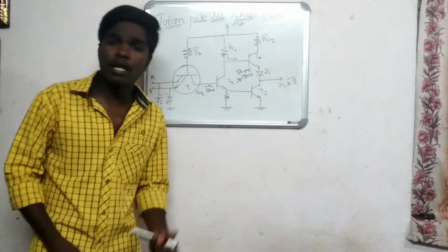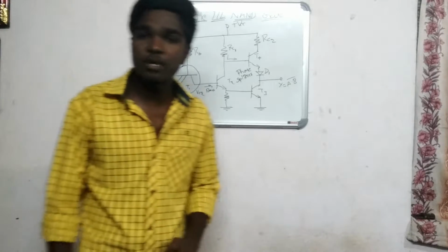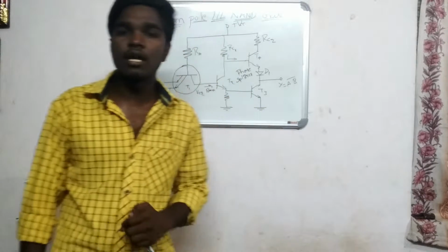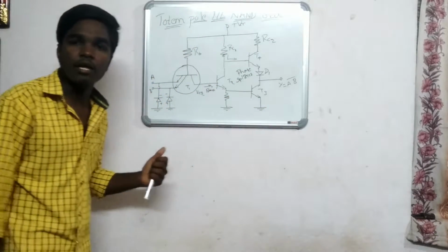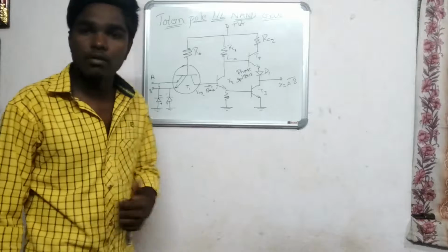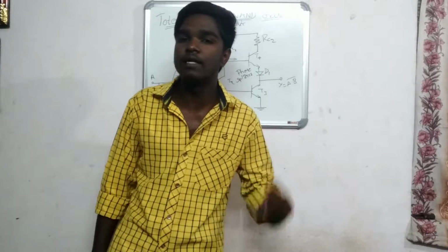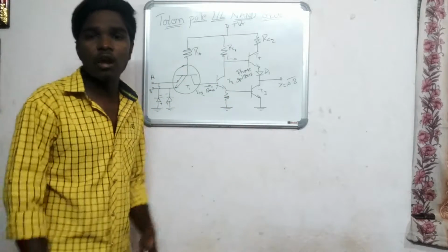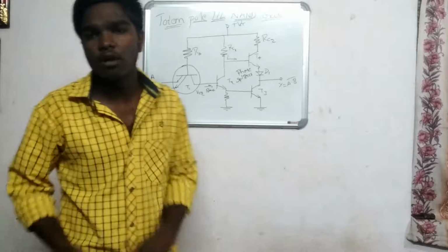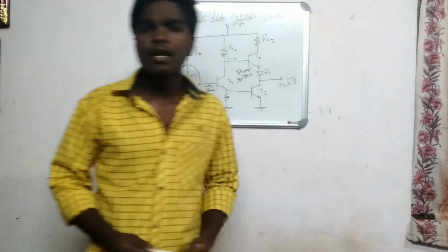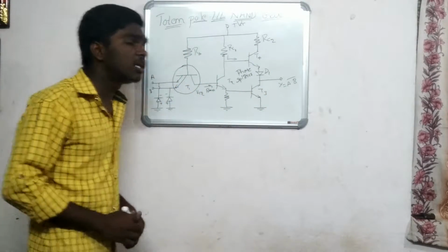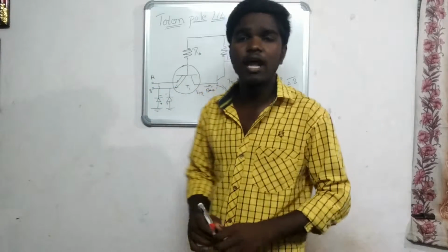We already discussed that the specially designed double emitter transistor T1 is arranged at the input side, and in this type of TTL NAND gate we are using three transistors T1, T2 and T3. When both the logics are low, or any one of the logics is low, then the transistor T1 will be in on state.